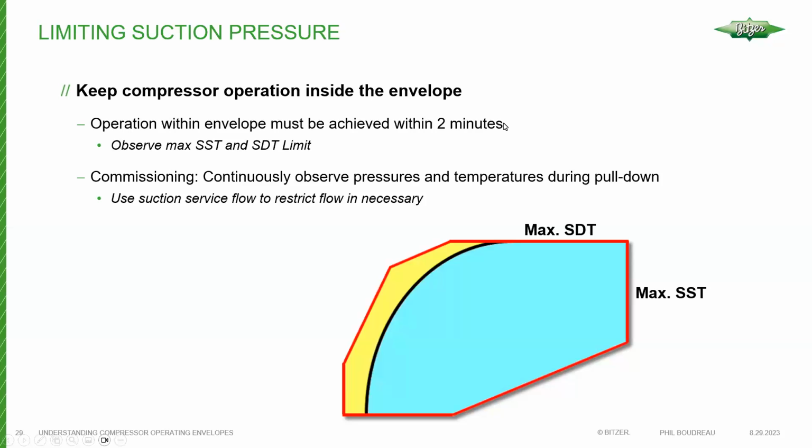Okay, and also when you're operating at very high suction pressures, it follows that your saturated discharge pressures are going to end up being higher as well. And there may not be enough condenser surface available on the system to reject all the heat, making things very complicated for the compressor and reducing the life of the compressor.